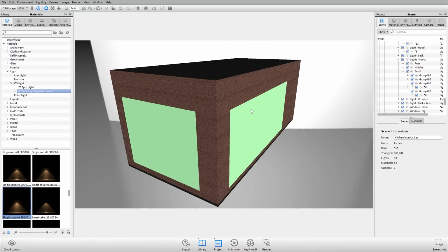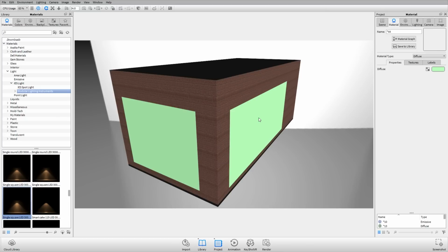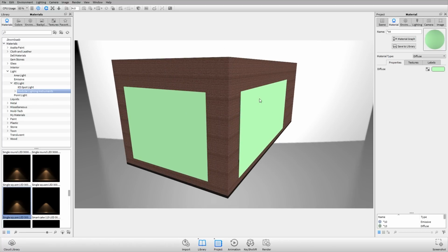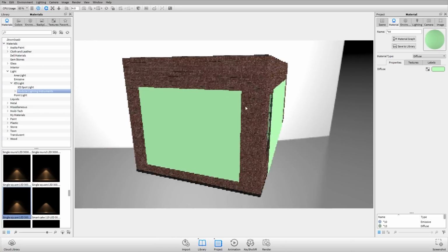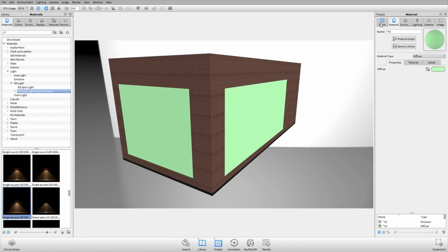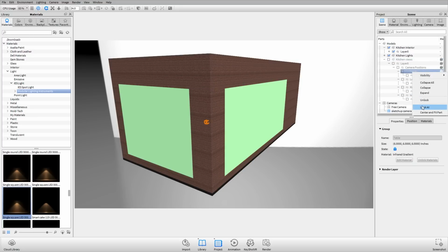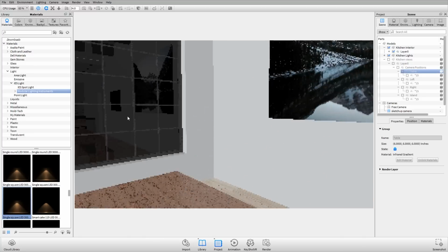And the request that we get is you want this really cool light. It's not coming from the sun, it's coming essentially from the sky and kind of diffused light. So we plan for this by just creating these big light planes outside our window, slightly offset and slightly larger than the window itself. So what I'll do here is zoom my camera in on that little placeholder I had above the table. I'll right click and hit look at, and let's zoom in so that we can see these windows.